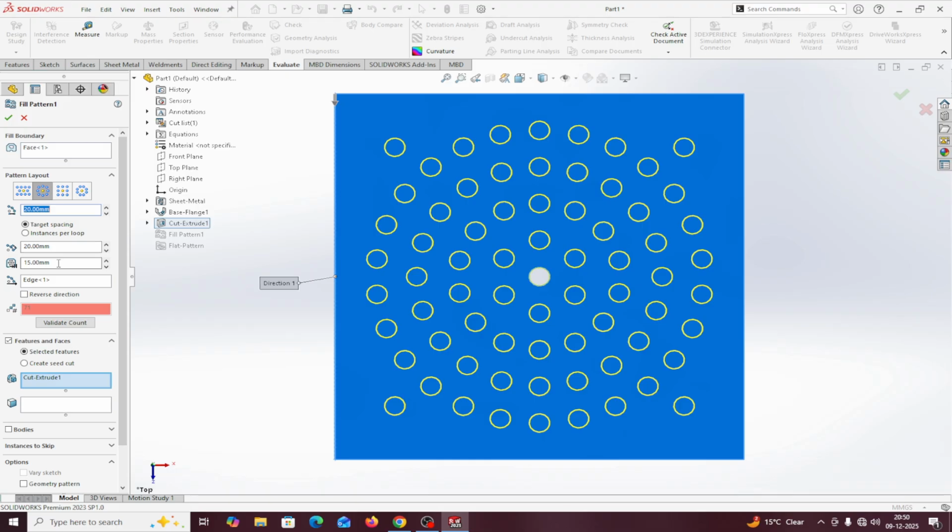Okay, this is the margin. I have already told you, 15 mm means there will be no instance at a distance of 15 mm from the corner edges, these edges, these edges, and these edges. At a distance of 15, there will be no instances, or it will be more than 15. But at least at 15 mm distance, there will be no instances. This is the meaning of margin. Suppose any instance comes beyond 15 mm, because it is cutting the margin line, so that doesn't appear.